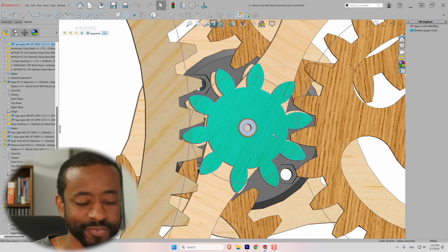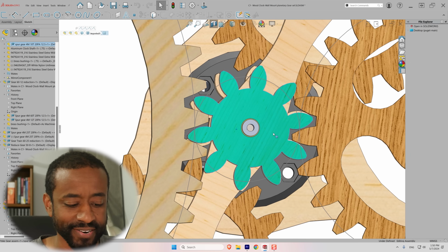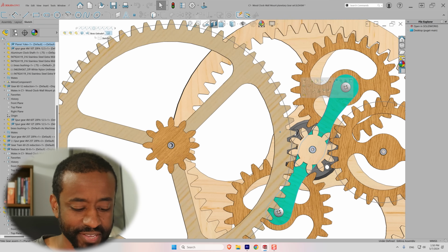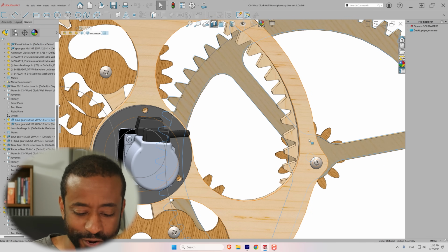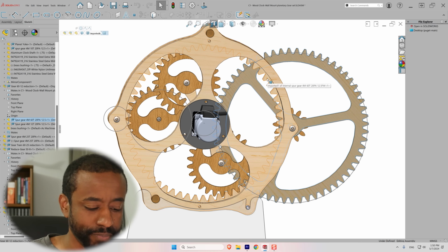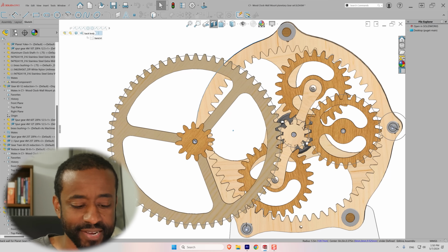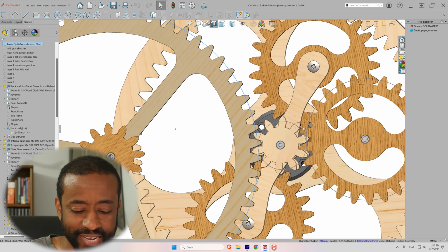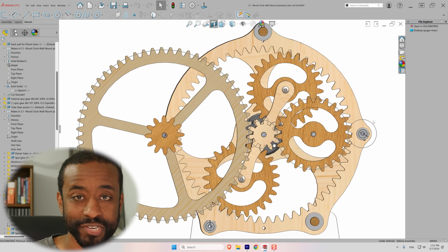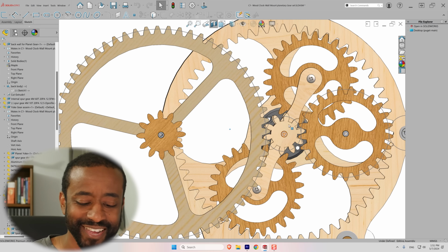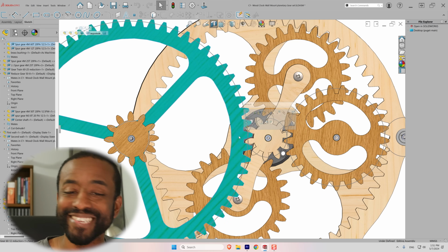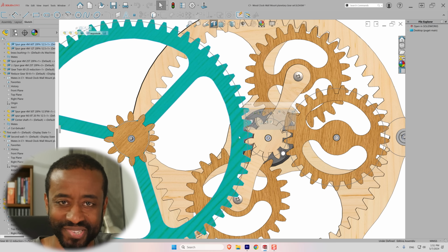This one has to be directly in the center line of the clock because it's connected to the yoke. This one has to have a mounting point that falls on this back wall, but you can see I've got some big holes there. What I did is at first I started manipulating diametrical pitch. Changing the diametrical pitch affects all 3 of the gears, and changing the number of teeth for this center gear affects both of these gears. And so there's a really interesting challenge here.